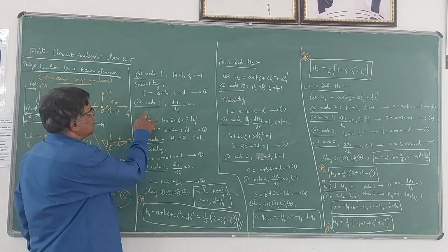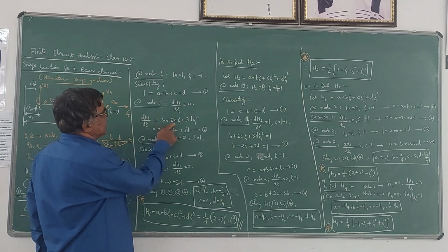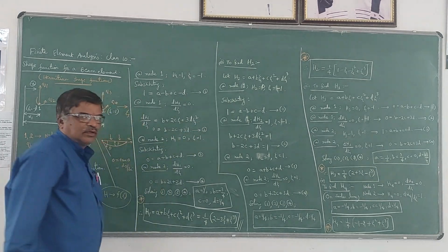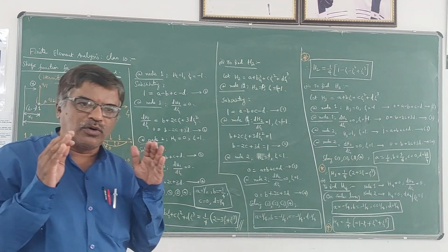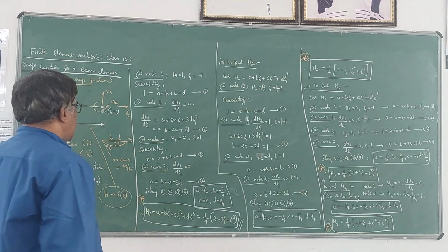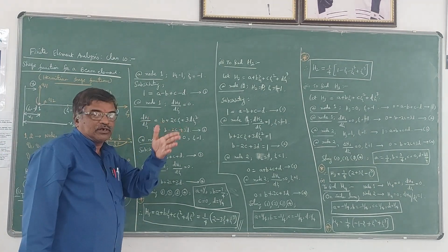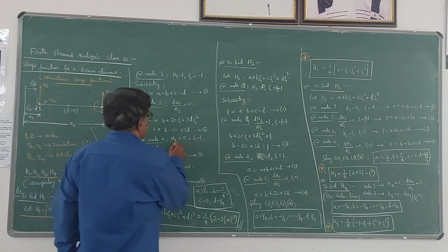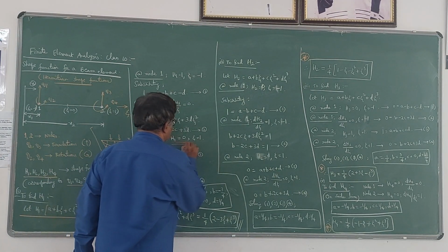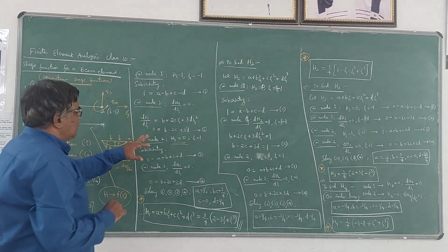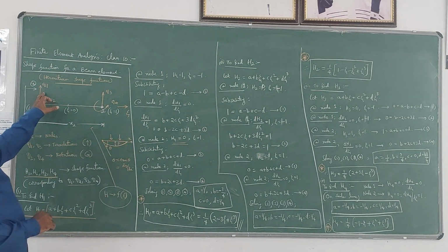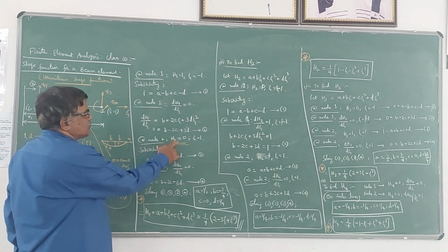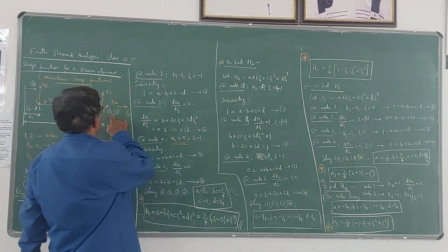Since I know this is 0, LHS becomes 0 here, and zeta you have to put minus 1, so you will get another equation. So at node 1 you have got 2 equations now. Now we will move to node 2. The difference is at node 2 the value of h1 becomes 0. This is because h1 corresponds to q1, so I have to take the other displacements as 0, so this becomes 0, but only thing is zeta becomes 1 here.